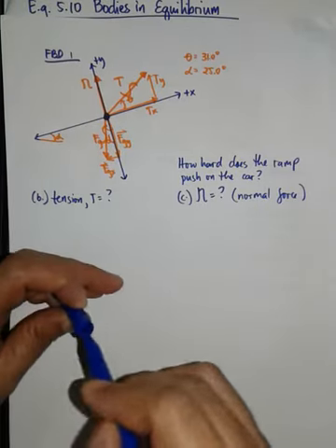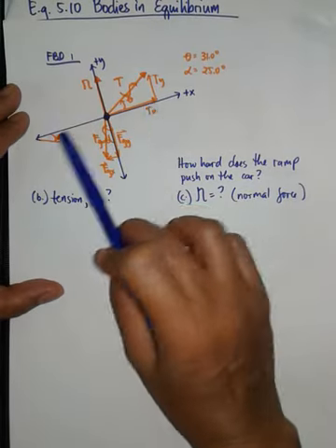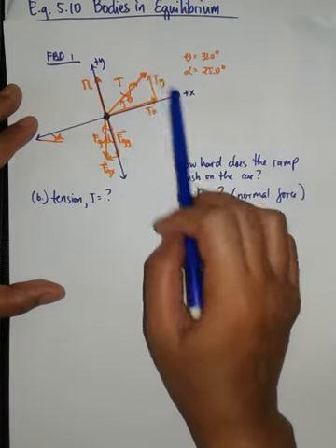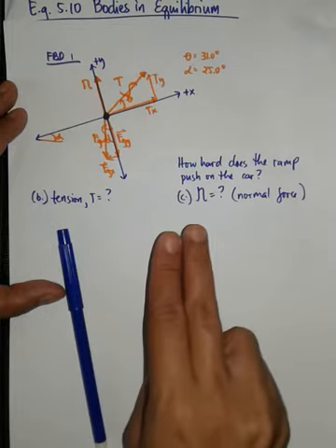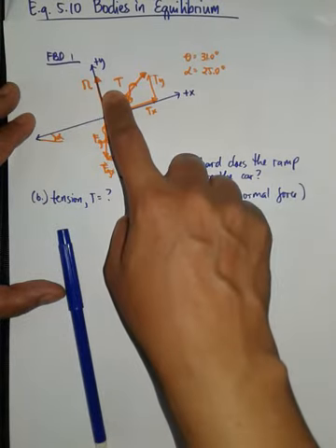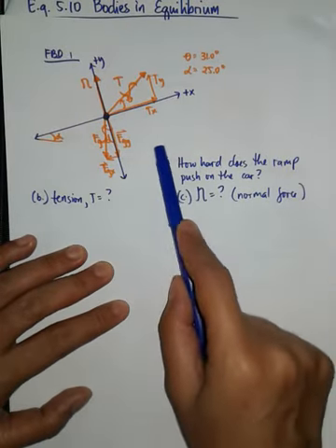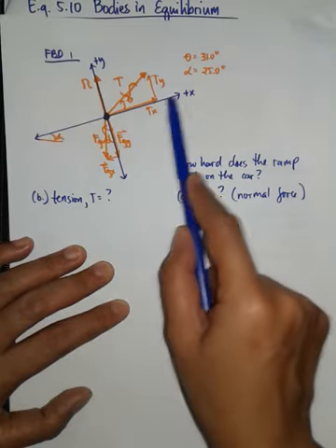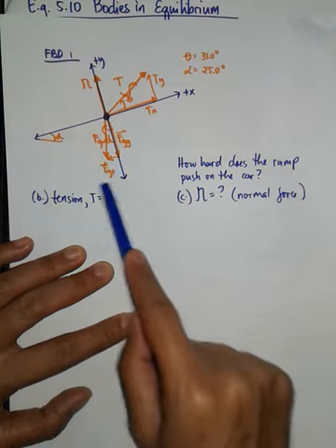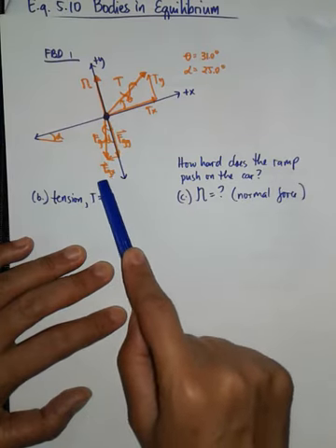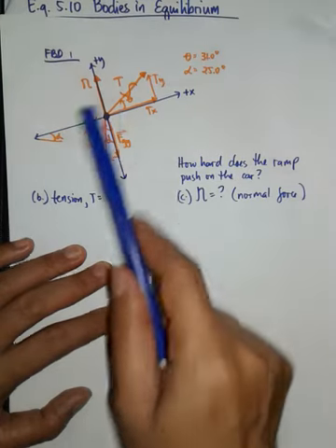Now, if you look in your free body diagram, merong component si T na nasa x-axis, meron ding component si T na nasa y. So, it's an indication that there are two possible options to solve for T. Pero take note, kung titingnan mo yung FBD mo, mas madaling gamitin si x-axis kasi si Tx lang ang unknown, itong si FGx known na yan kasi alam natin yung mass at saka alam natin yung acceleration due to gravity. Okay? Kaya, gagamitin natin si x-axis.